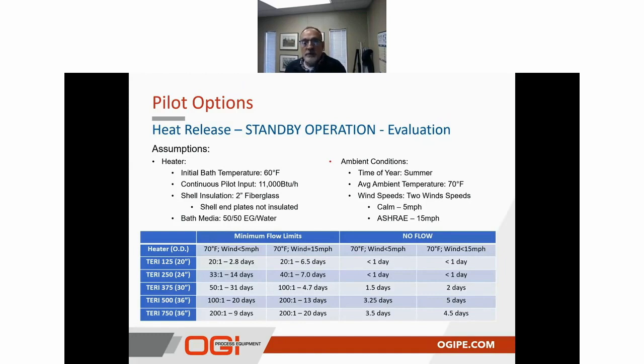On the no flow situation, this basically is saying I'm not going to allow any flow of natural gas through the heater, even naturally. There's for a fuel gas application, if a turbine downstream or a user downstream is completely offline, you'll have a static operation of the heater where basically the heater is going to have to survive on its own without any type of additional control.